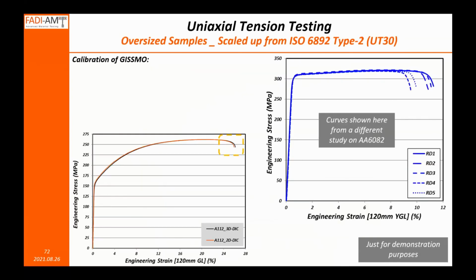And what typically happens is that we take these endpoints of the stress strain curve or the load displacement curve, and we use that descending portion of the curve to obtain certain parameters, like the decaying factor for a fracture model, and so on. And those deviations that you see there between 2D DIC and 3D DIC are actually, in most cases, much smaller